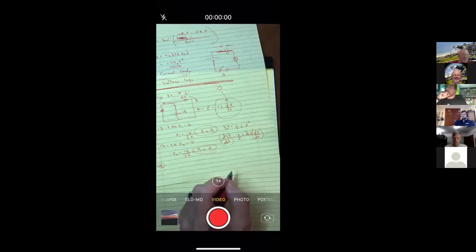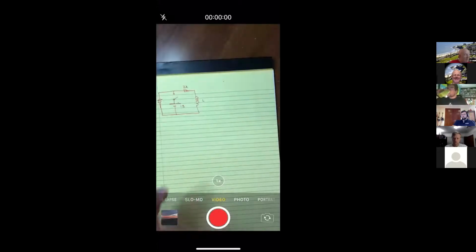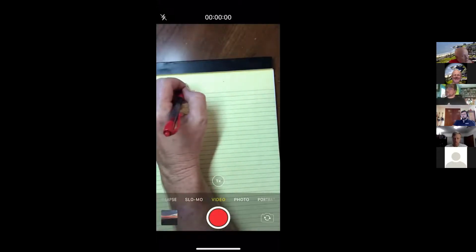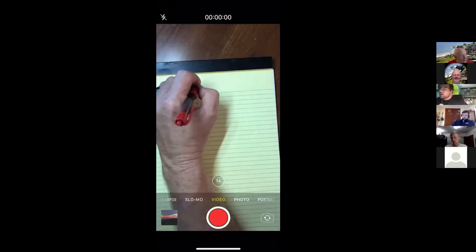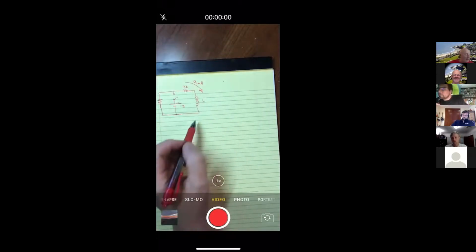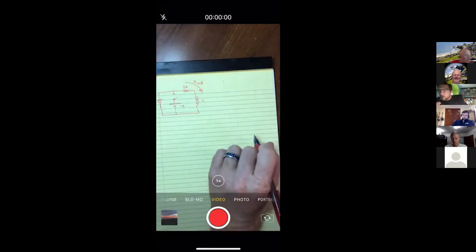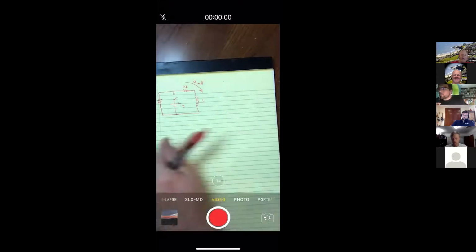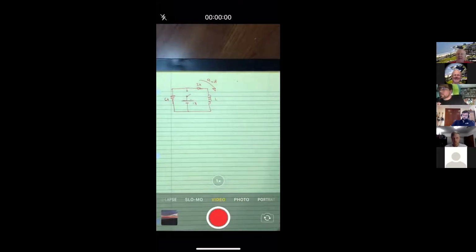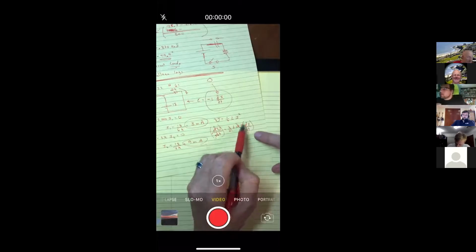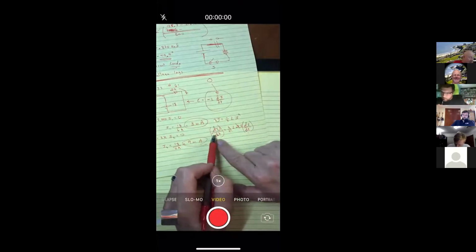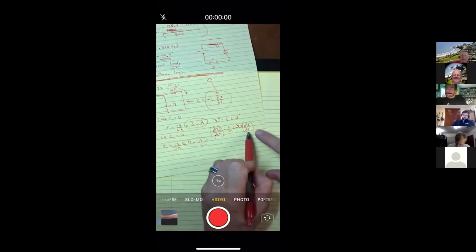In this case, we already set up that there is 9 milliamps going around this right-hand loop. So when you open that switch, it could not go from 9 down to, say, 7 instantaneously, or 9 down to 0, because a change instantaneously is really an infinite derivative. So it takes an infinite amount of power to change this infinitely quickly.